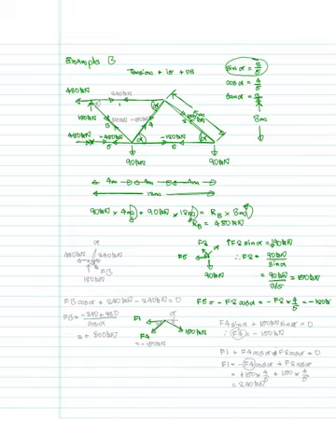So from there we get F4 sine alpha. Remembering that that angle there is alpha, if you add that onto 150 kilonewtons, also times sine alpha, bearing in mind that that angle there is also alpha, equilibrium tells you that needs to be equal to 0, and therefore F4 is equal to negative 150 kilonewtons.